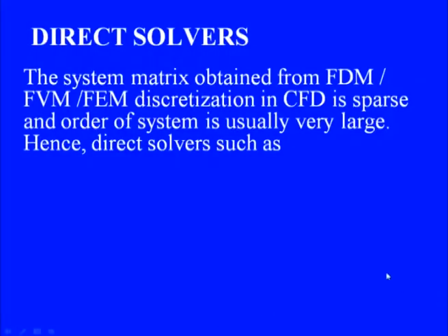Now let us have a look at our specific case of FDM, FVM or FEM discretization. When we apply any of these discretization schemes to our governing equations, what we get is a sparse system, and as I just mentioned, the order of the system is usually large, in millions and billions. Hence direct solvers such as Gauss elimination or LU decomposition are rarely used.